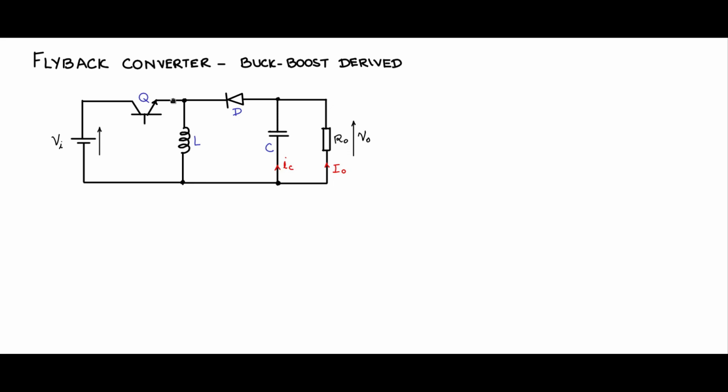The emitter is lifted up, floating. It is much better to have the switch ground based, and a ground based drive is much easier to make. So without loss of generality, we can move this switch from the top rail to the return rail, maintaining the flow of the current path in the same manner.